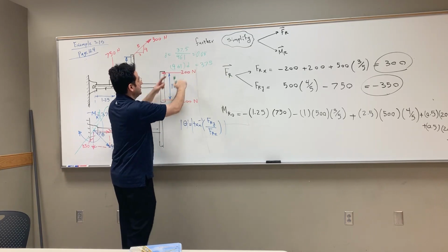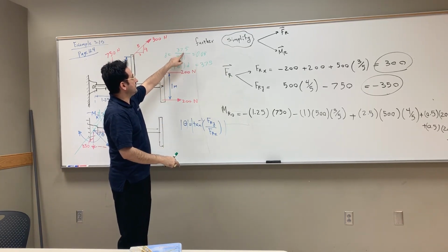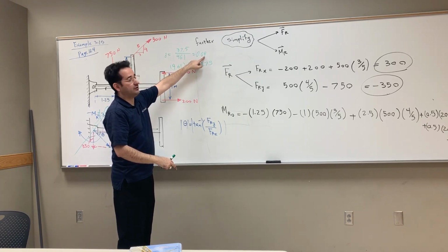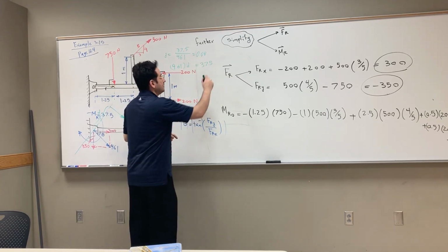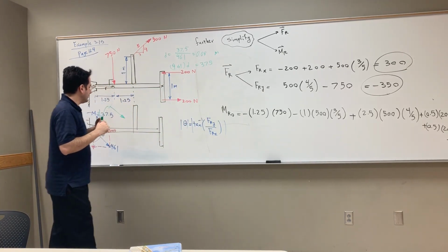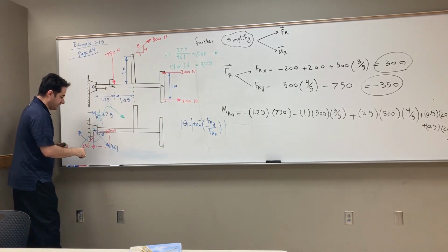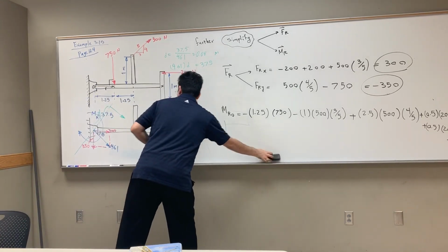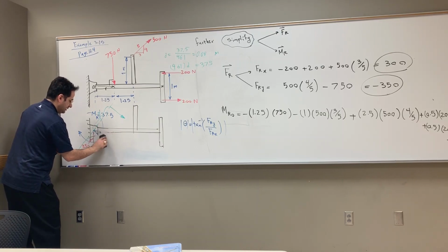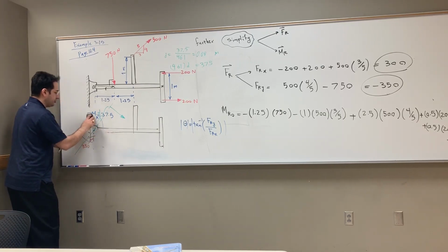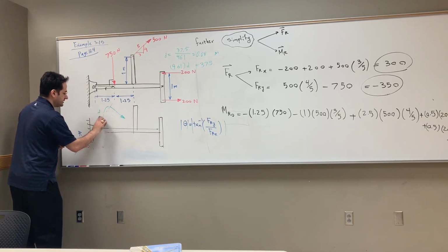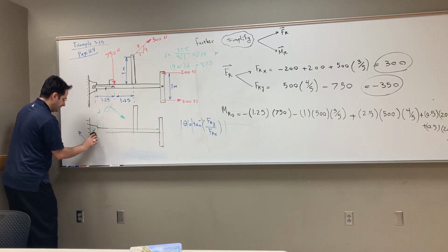If you solve for D, D is equal to 37.5 divided by 461, which is 0.08 meters, right? Almost 80 millimeters. So in that case, I can further simplify this force. I no longer need a moment because my force can generate that equal moment, right?